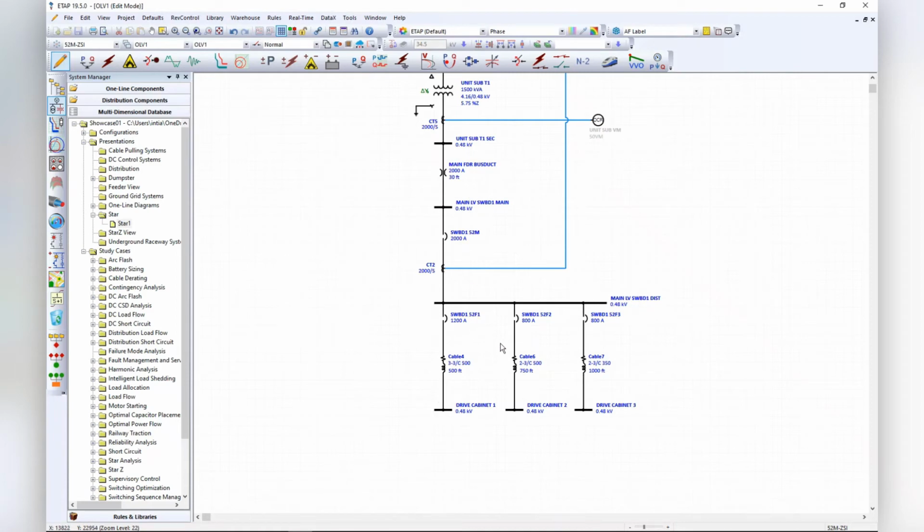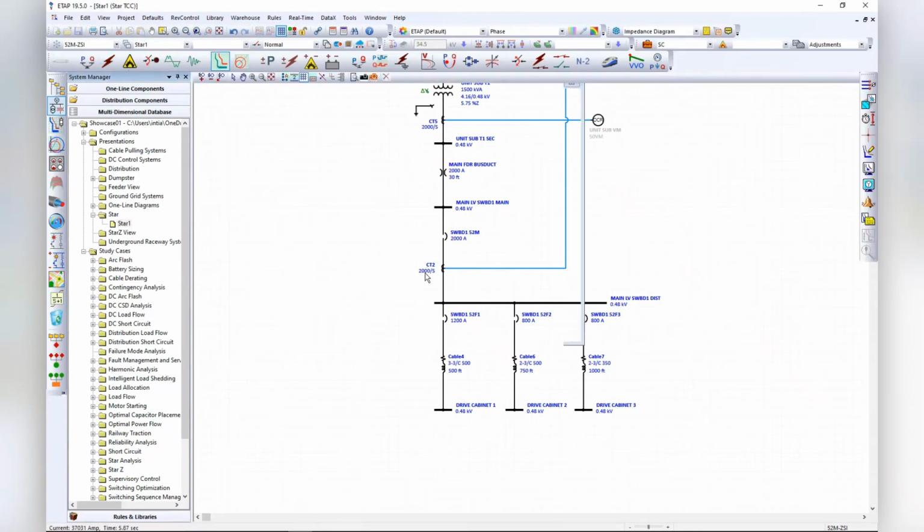Now, the explanation for that might be very simple. The explanation might be that these breakers, when they come from the same manufacturer, in the majority of cases, have been tested to be selectively coordinated in the instantaneous region. That means that when they run 10,000 tests on these things, they can almost guarantee that the feeder instantaneous is going to trip way before the main instantaneous in that combination. That may be the reason why, but let's go to the TCC, and here you're going to see it.